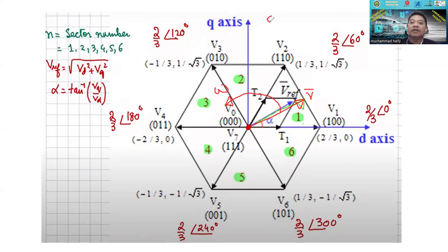The final goal of the calculation is to make the rotating magnetic field of the stator the same as the rotor rotating speed, and the shift between the rotor and the stator vector direction is perpendicular, I mean 90 degrees. That is perpendicular, to achieve the maximum torque of the motor.